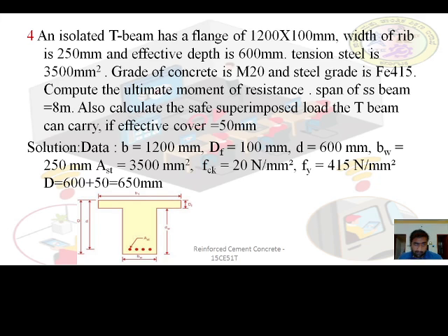So next beam. Here actually once again it is a T beam, an isolated T beam. Isolated T beam means that in the T beam the slab projected on both sides, on either side, will be discontinuous, that is, it is ending. It is not extending to the next beam. Like this, there is no extension. Here only the slab is ending. So that is the new case.